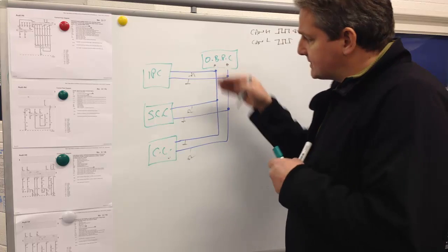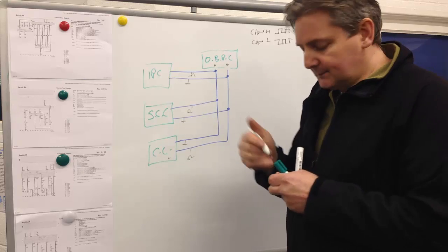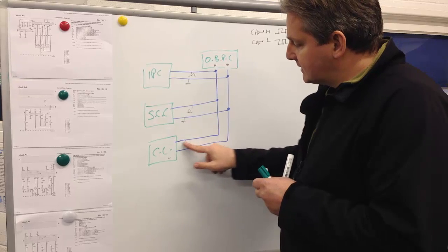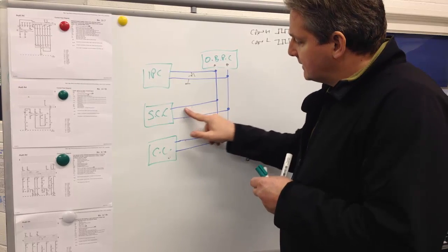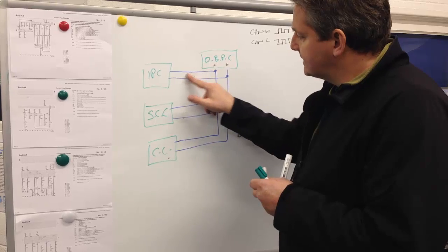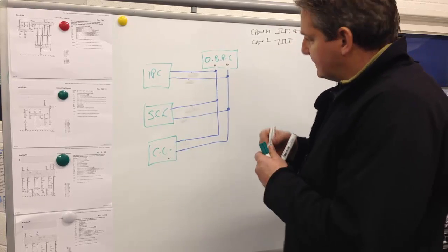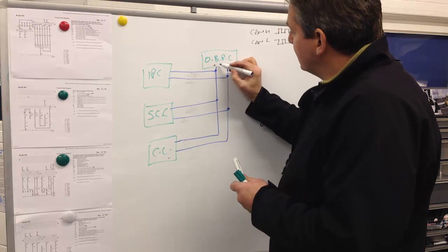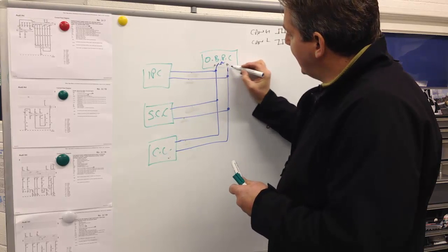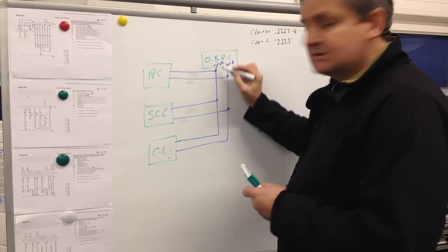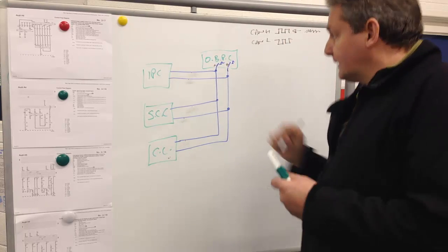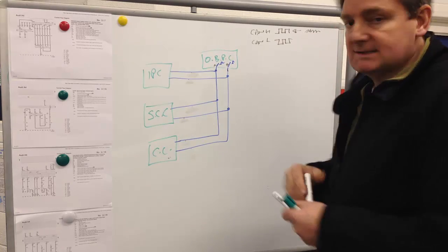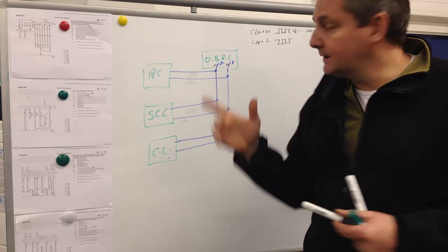The fact that that isn't present when we're disconnected, the waveform looks absolutely good when we've disconnected from the unit, leads us to consider two root causes. Root cause number one is we have a problem inside the module. When it's connected up to our onboard power supply unit, we are expecting some form of error, maybe resistance internally. When we connect it in, it's pulling that CAN high and making the waveform become disrupted. That's our first concern. That could be inside the module.